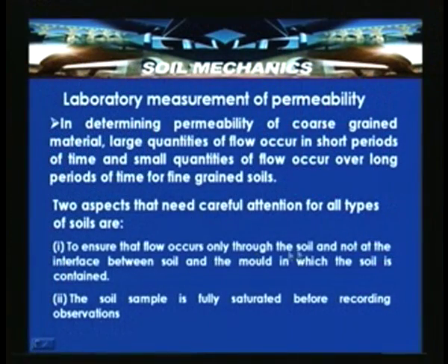Otherwise, the air in the voids of the soil mass can influence the permeability value, and can interfere with the flow channels which are developing through the soil mass. So, here are the two aspects: one is to ensure that the flow occurs only through the soil, not at the interface between the soil and the mould in which the soil is contained, and the soil sample is fully saturated before recording observations.